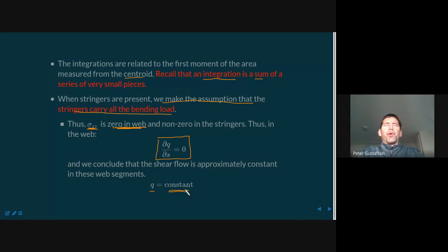And so you get this circumstance where, when you assume that all the load is carried by one, it's the worst case scenario for the bending load carrying members. Any amount of load that would be carried by the thin-walled members would decrease the stresses in the principal load carrying members. So it's a conservative approach. And vice versa, the other way also applies. We're going to assume in the future that the principal bending members don't carry any torsional load, and of course, we recognize that ultimately they will carry a little bit.